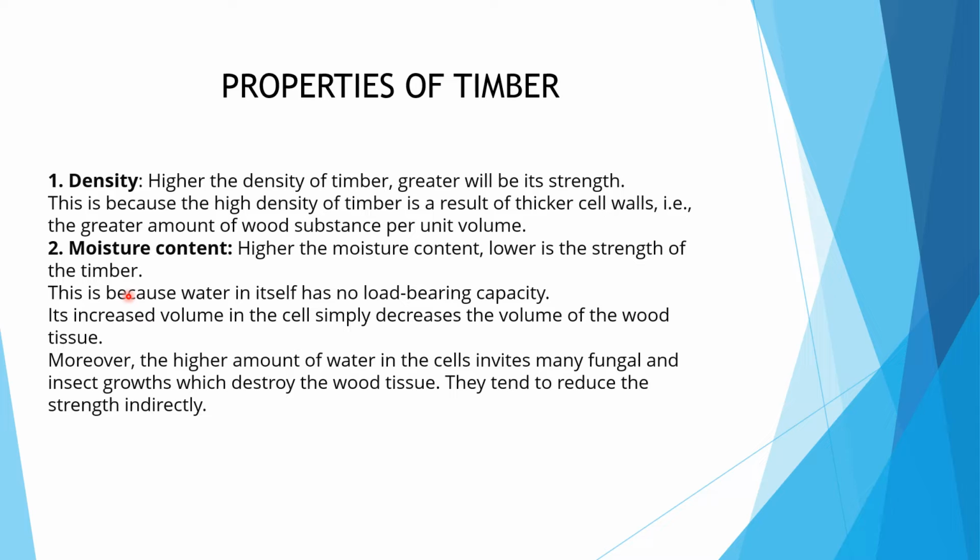This is because water in itself has no load bearing capacity. Its increased volume in the cell simply decreases the volume of wood tissues. Moreover, the higher column of water in the cell invites fungal and insect growth, which destroy the wood tissues, so they tend to reduce the strength indirectly.